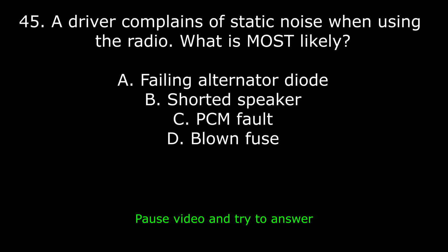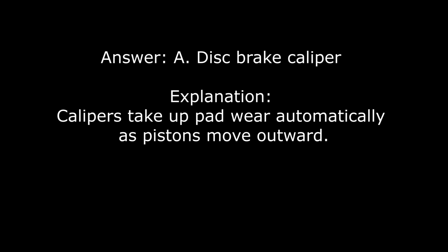45. A driver complains of static noise when using the radio. What is most likely? A, failing alternator diode. B, shorted speaker. C, PCM fault. D, blown fuse. Answer: A, failing alternator diode. Explanation: bad diodes create AC ripple, heard as static in radio.